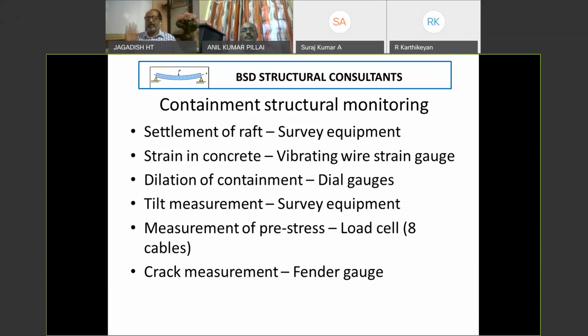Concrete is poured over the strain gauge. We always take care wherever there is a strain gauge, vibrator is not anywhere near that area, as this will damage the strain gauge. So all the strain gauge wires are then connected to control room, and from there we measure strain in concrete during testing, right up to 1.8.